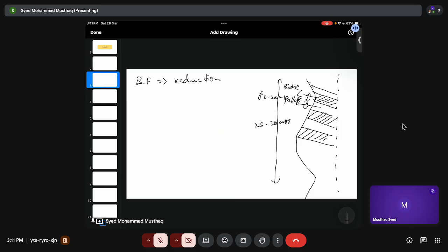And then you heat it to 1000 to 1200 degrees centigrade so that it becomes hardened. And then pellets have good porosity because whatever binders you are using try to escape and they become porous. Okay. So it has very good porosity when compared to your sinter.